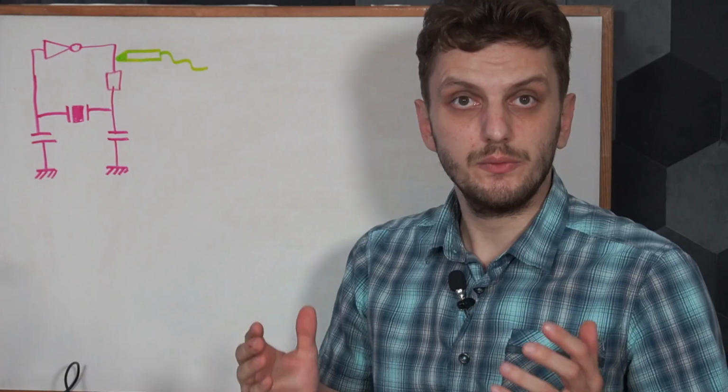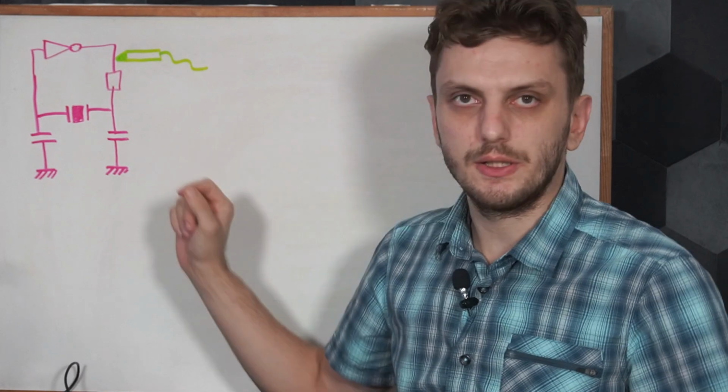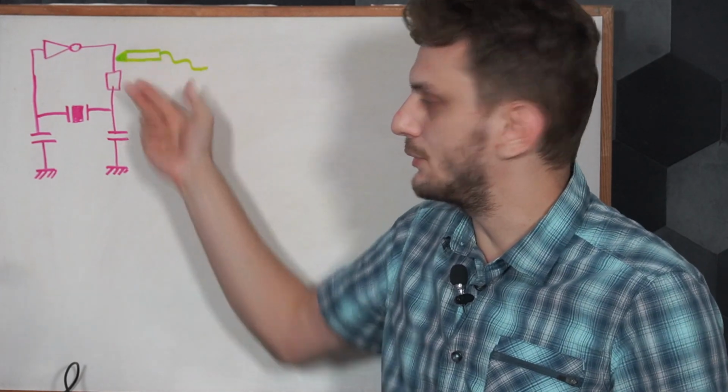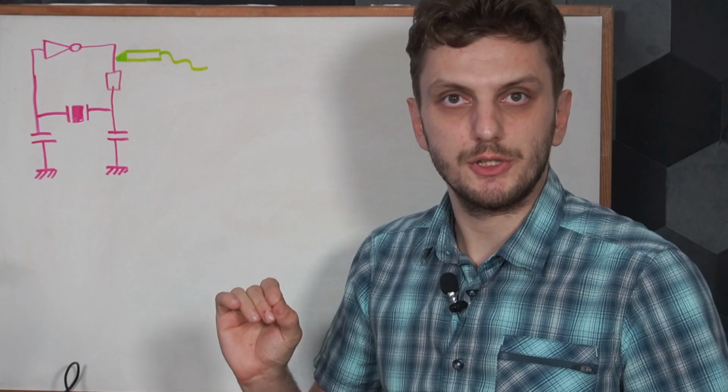Now, the delay time can be important if the system startup is critical. So if a microcontroller-based circuit needs to operate quickly after power on, you want the startup time to be quite short. But on the other hand, long startup time can also be indicative of some other hidden issues, like a low oscillation margin. Now, this measurement is carried out by directly probing the oscillator output pin before any series resistors, if any, are present. And this is where the problem starts.